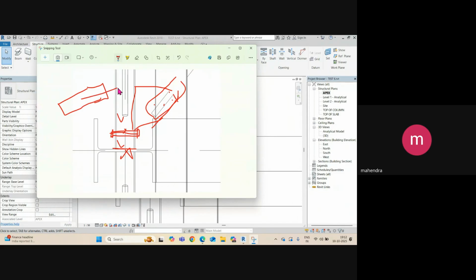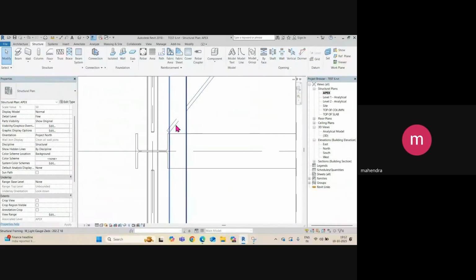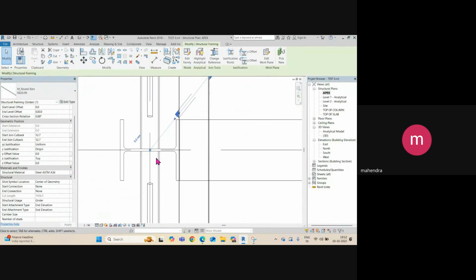And then your rod should be welded to this plate, right? And your gusset plate is like that. Suppose this is your column, and then you need to give the two bolts. So here a 10 mm gap. This type of connection you can develop here. So you can change your working point as per your requirement.